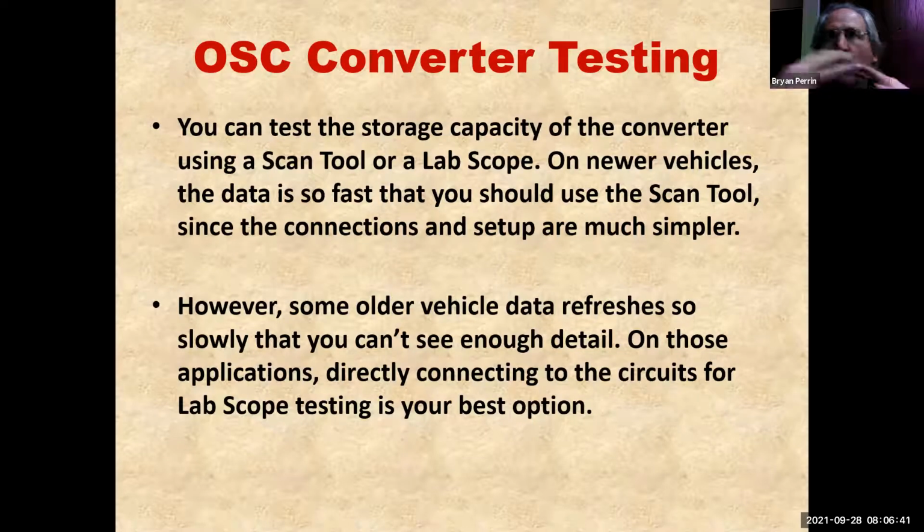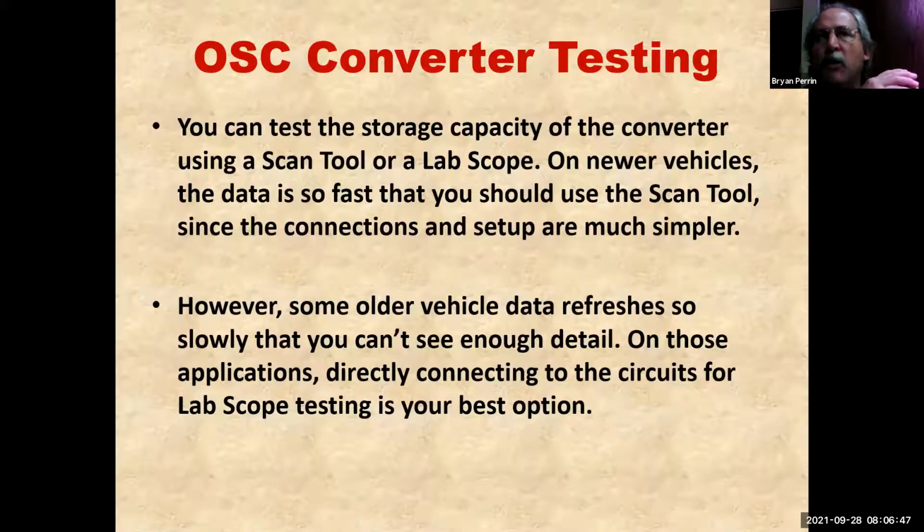This is where we're, again, trying to make some high level decisions here. We kind of use a phrase: is this the rabbit you want to chase? Before you really go down the rabbit hole and chase it, you want to make sure that other high level tests lead you in that direction. As I discussed, high level tests aren't just for high level tests. They're tests that we can look at from a distance to give us an area on where we need to go pinpoint testing. Traditionally, automotive repair has taught pinpoint tests.